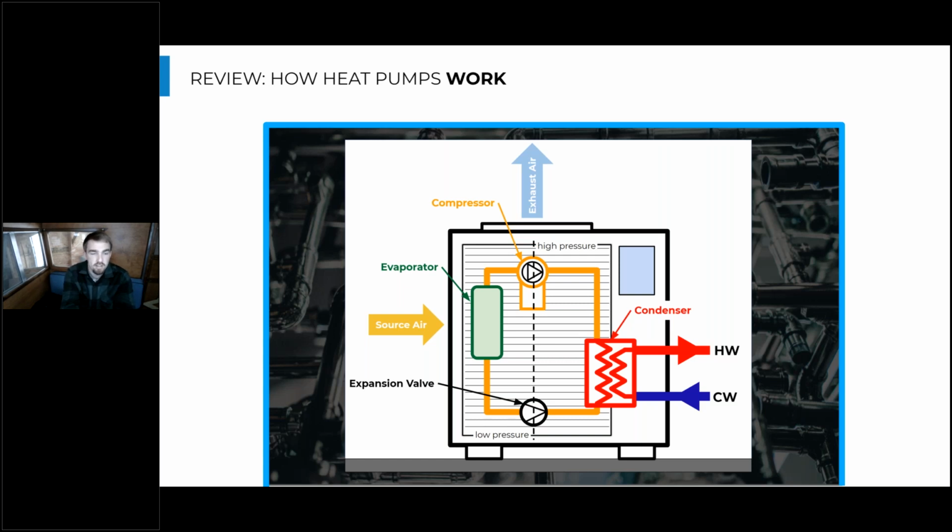It's due to the characteristics of gases that this refrigerant is in a good portion of this cycle. As soon as a gas is pressurized, it will rise in temperature, and if it drops in pressure, it will then lower in temperature. So you might have seen this in practice. If you're spraying your keyboard off with dust off, that spray can actually gets really cold, because the gas in the spray can has dropped in pressure as you expel a lot of the gas out of the can, right? So the can itself gets really cold due to that pressure drop.